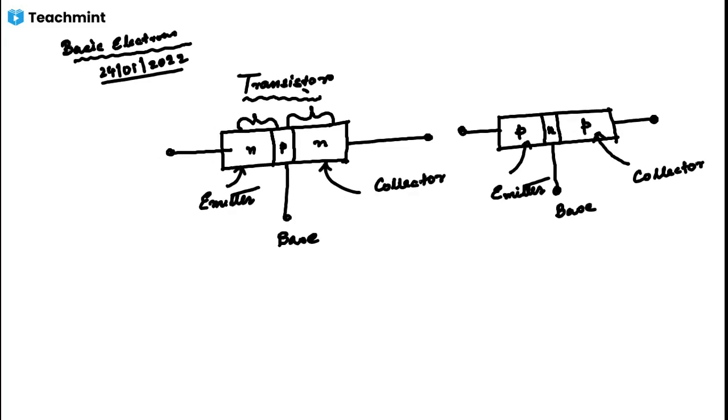Same for the collector, the section on the other side that collects the charge is called the collector. The collector is always reverse biased. If the emitter is forward biased, then the collector must be reverse biased. Its function is to remove charges from its junction with the base. The collector of a p-type PNP transistor has a reverse bias and receives hole charges that flow in the output circuit. Same as for the collector of an n-type NPN transistor, which has the reverse bias and receives electrons.